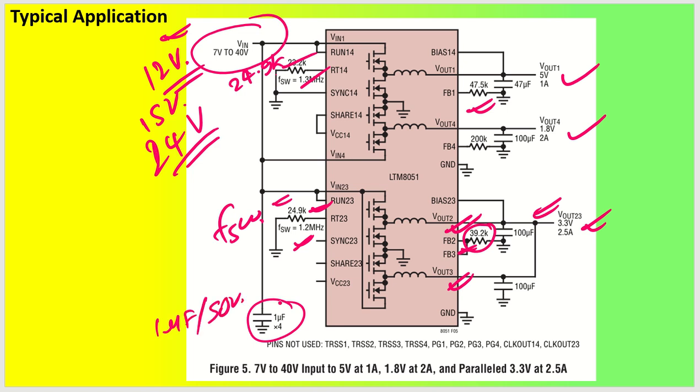Okay. I'll add here, put 10 microfarad in each one of them respectively, plus 0.1 microfarad also with 50 volt rating each one of them. 10 microfarad, you can keep for 12 volt rating, you can keep up to 25 volt rating, no problem. If you have an input of 12 volt, then you can keep it 25 volt rating. So this is the complete design that is there.